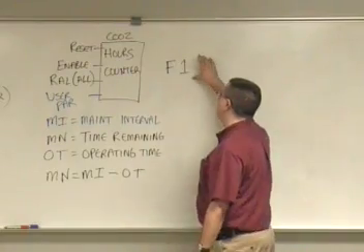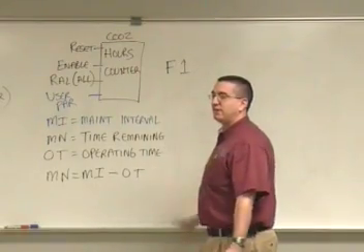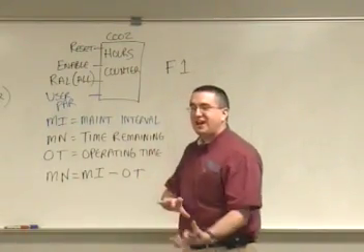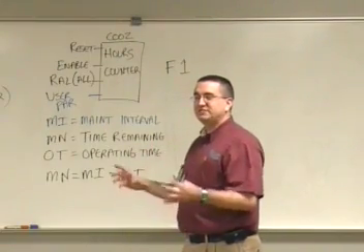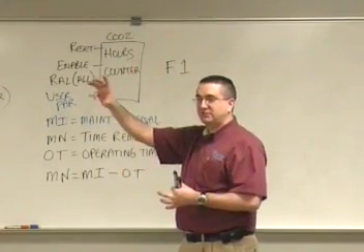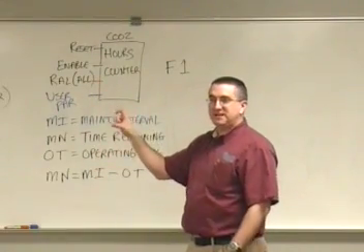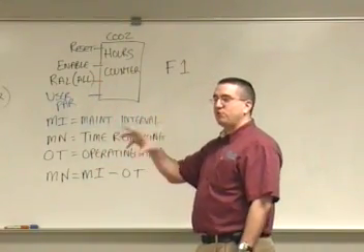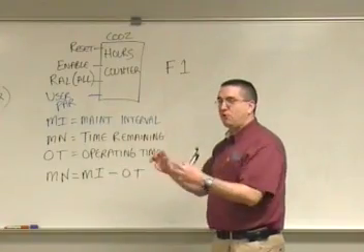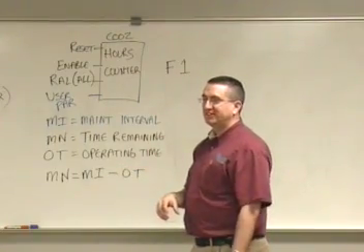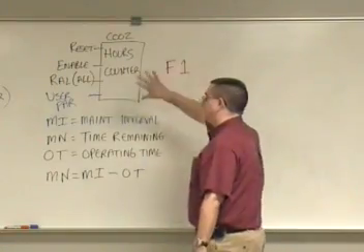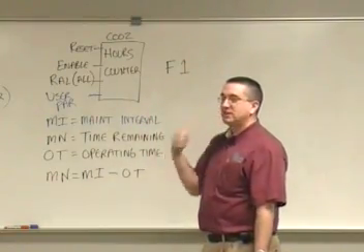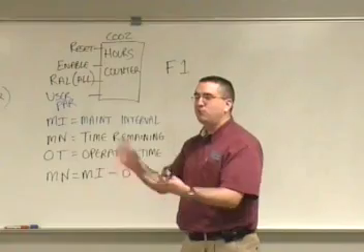And the nice thing about most PLC software is that when I click on an instruction and hit F1, it talks about the instruction and then gives me a little bit of sample code. It's going to show you an example of a program using that instruction. So now if I ever want to use that instruction and I don't remember what was talked about in this class, I can just go in there, hit F1 and say, oh, that's how they use that.